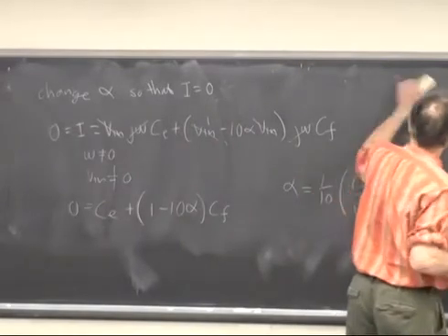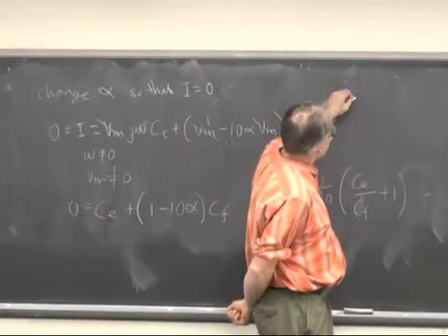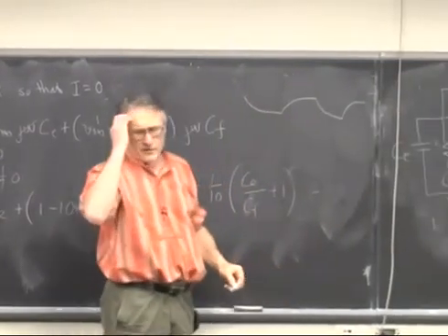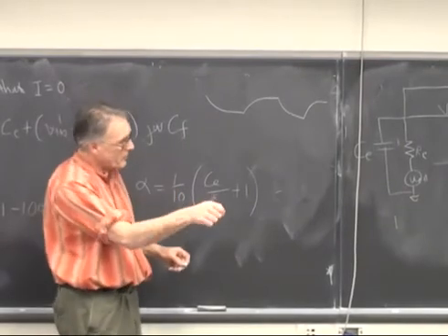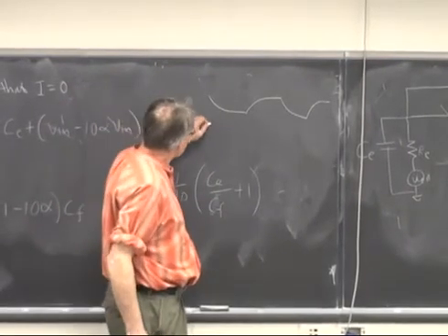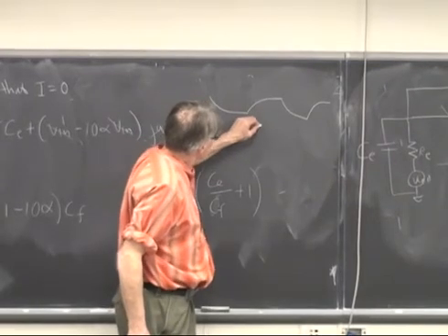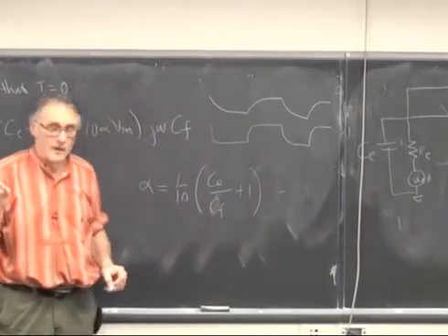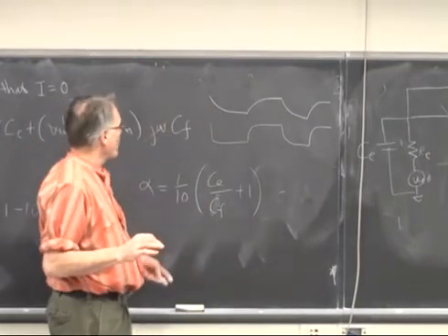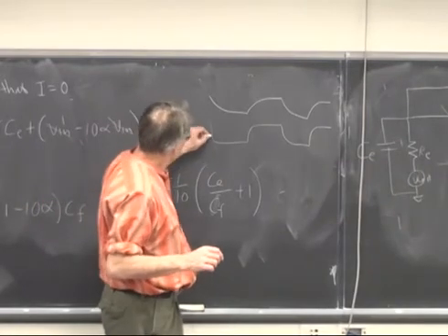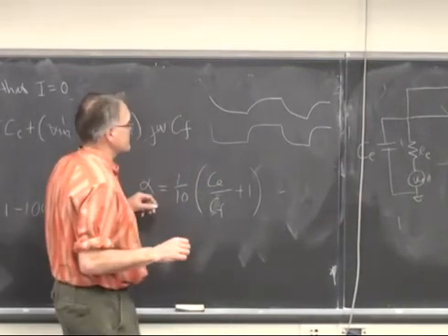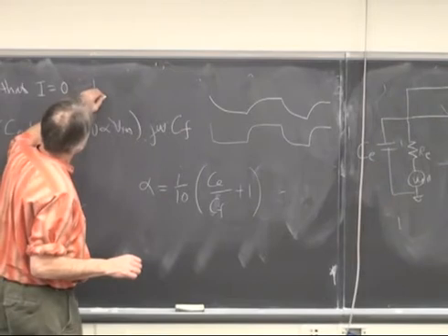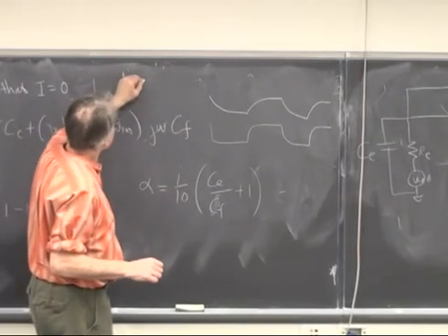If you were to start out with a waveform that looks like this, because you're putting a square wave into the system, and you start turning up alpha, you're going to get something that looks like this. You're going to lower the net time constant. You turn it up a little bit more, and a little bit more, and you're going to get something that looks like this.